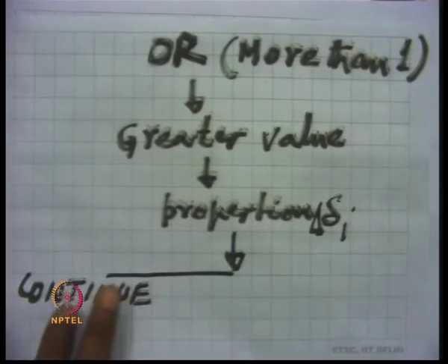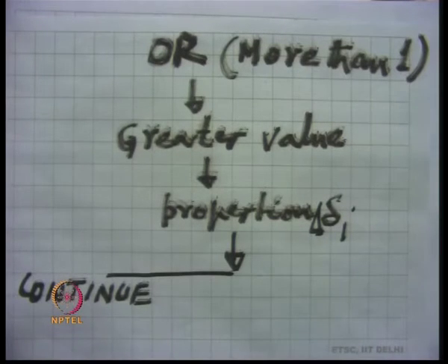So there we take the greatest value of the MP, and then we proportion the incremental displacement in such a way that the bending moment at that particular cross section just becomes equal to MP. In that case, for that particular cross section, Mi will simply be equal to MP. For other cross sections, obviously the values will not be equal to the value of MP